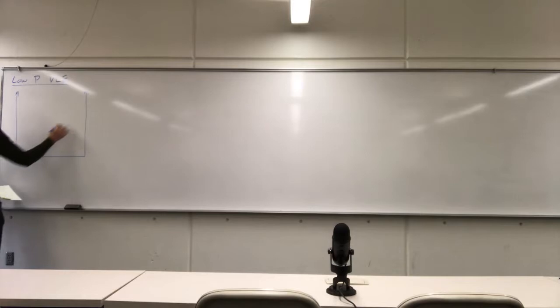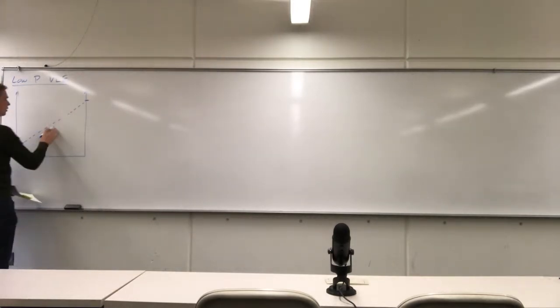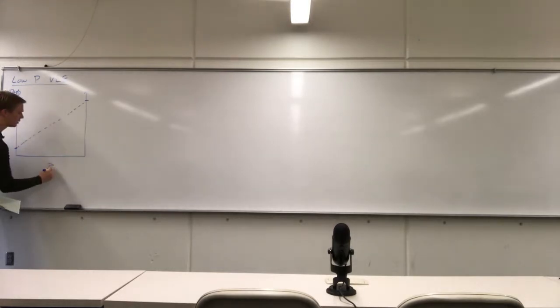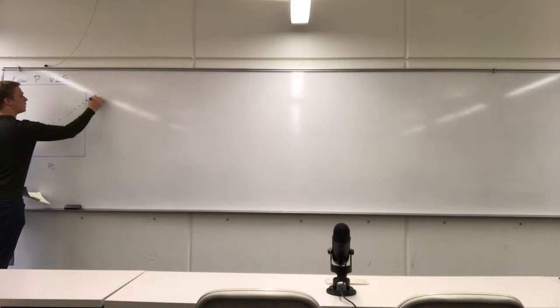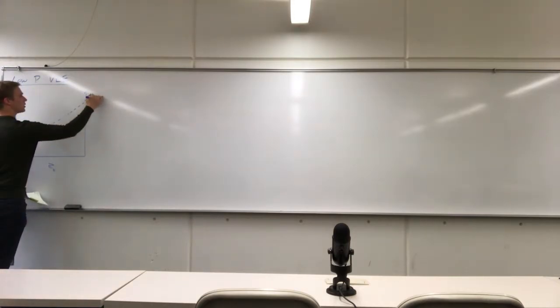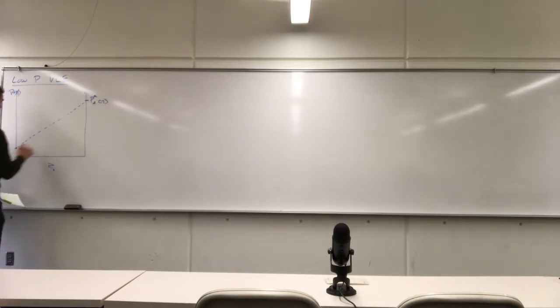So in the case here of a standard PXY diagram, the bubble curve is just going to be a weighted average. I'll do P, z, and A. I'll do A and B. So this is going to be the vapor pressure of A at whatever the system temperature is here. This is going to be the vapor pressure of B at whatever the system temperature is.